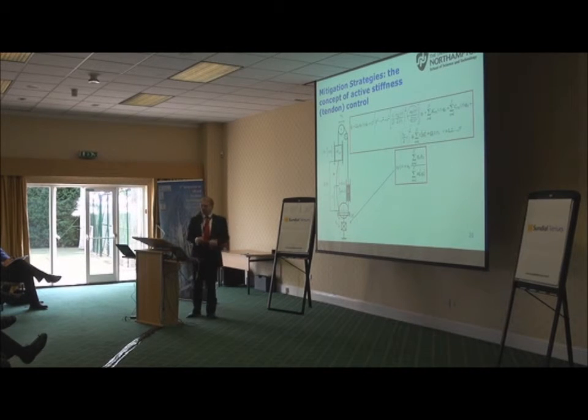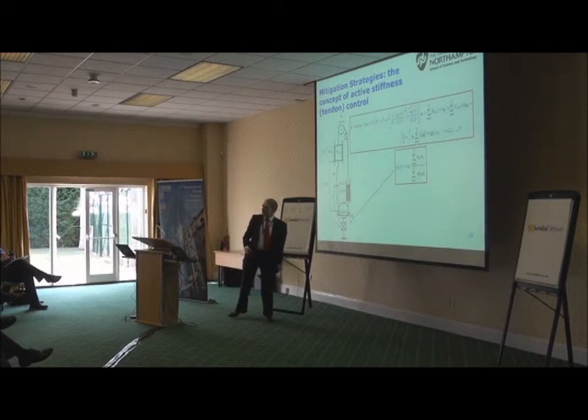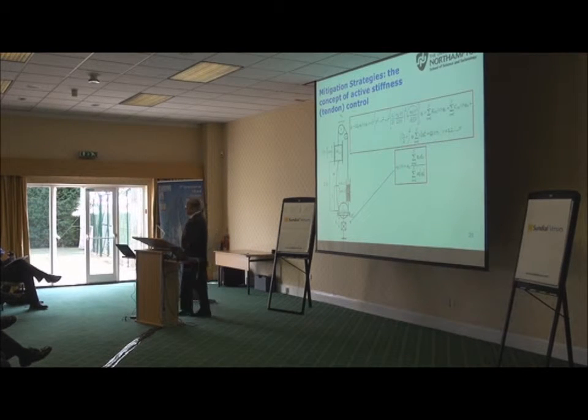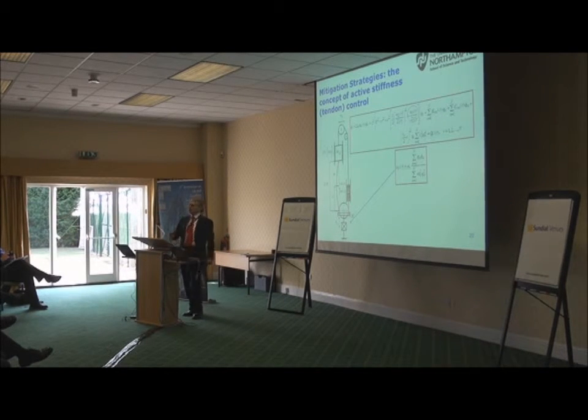In the case of the compensating rope system, what could be done is to apply the concept of active stiffness. What it means is that in this system here we have a compensating sheave, a rope vibrating, let's say at one side, the car and the counterweight, and we pull this mass at the bottom with, for example, twice the frequency of vibration of this rope, 90 degrees out of phase. And this sort of pulling motion can damp vibration of the ropes.